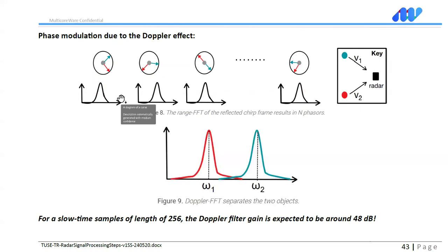You should get the same pulse, right? Because if the target is not moving, or not moving fast enough to change the range bin, then you should get the same phase. But this is not what's happening. Even if the radar is within the range, it's moving, before it's going out, you can have some number of pulses within that range. And what you're going to see is the phase is going to be rolling.